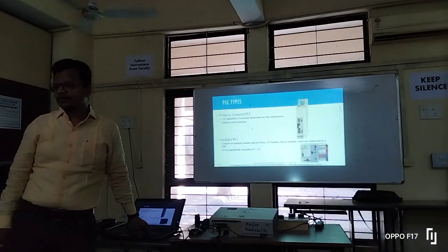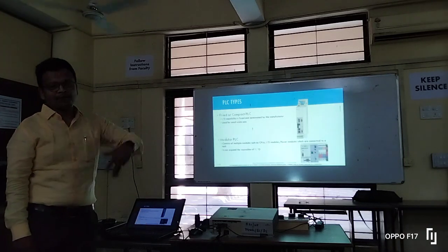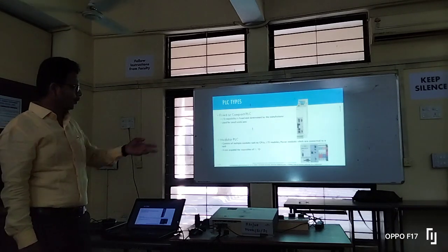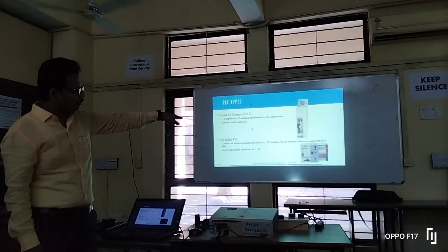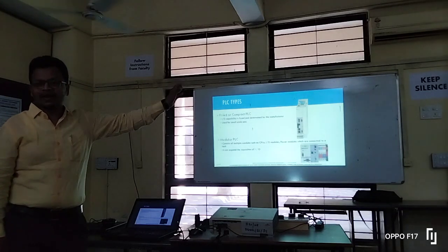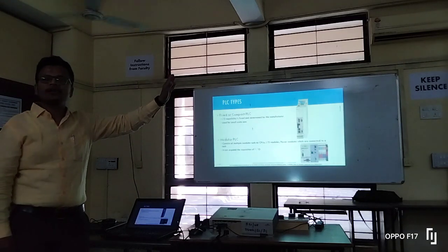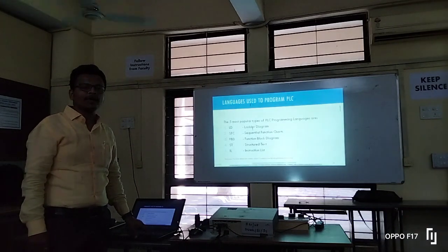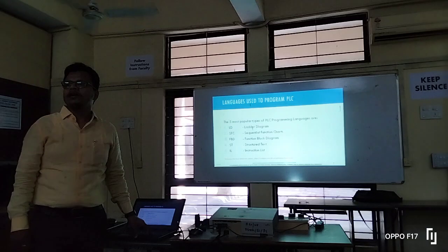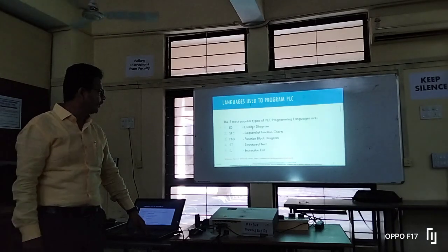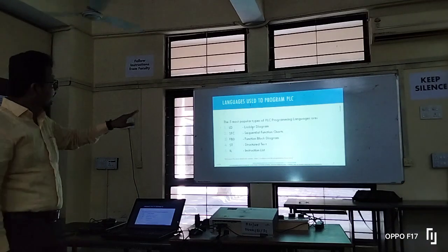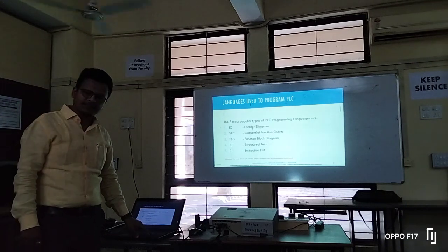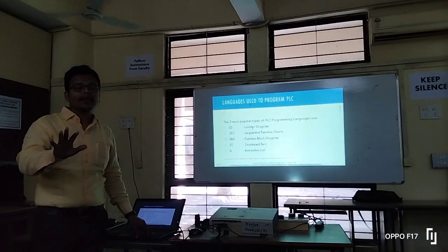These are the PLC types, fixed and modular. The difference between them: what is in fixed? A fixed number of inputs and outputs. And in modular you can vary that. You see the blue color and pink color modules, you can add and remove those modules, so that is a modular PLC. For programming you can use this many types of languages: ladder diagram, sequential function chart, function block diagram, structured text and instruction list. Instruction list is similar to your assembly language.